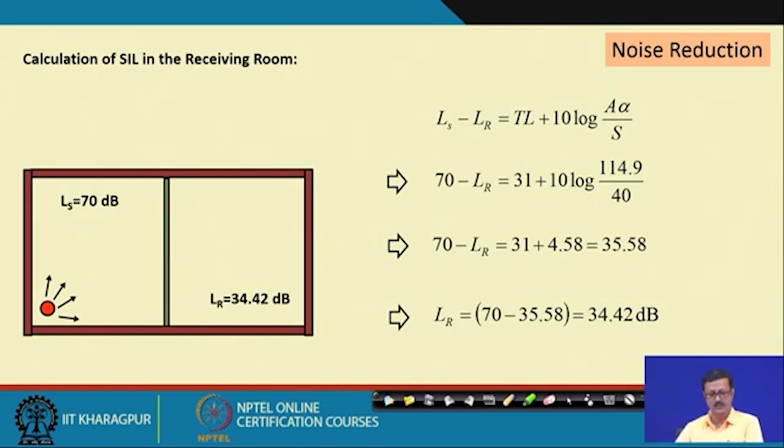because the level of sound expected here by transmission from 70 dB noise from the source room is 34. So, probably it may act as a machine room or some kind of a room like a laundry, where you see NC 50s and all can be permitted. So, something like that you may permit, but something like a reading room or classroom or maybe a hospital or other noise sensitive room, as per the NC recommendation, is not permitted in this particular area.